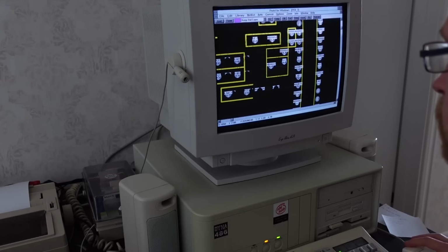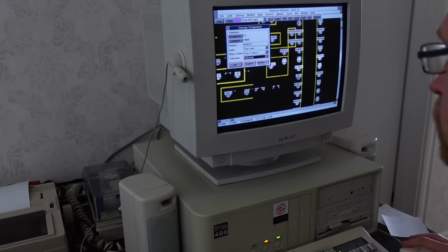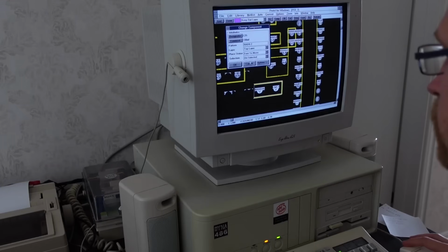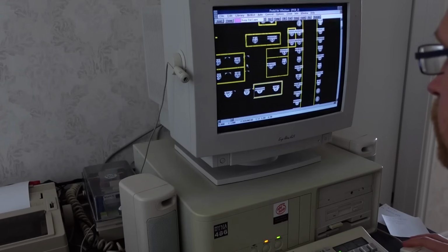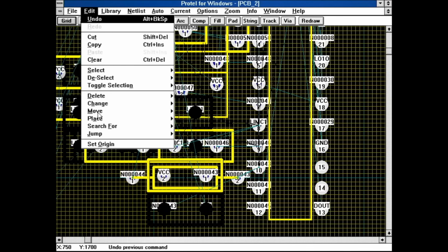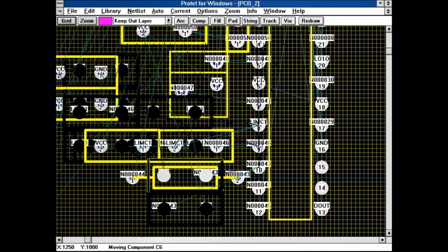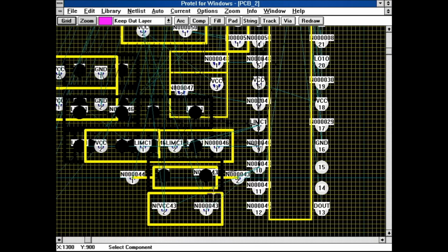Another fun quirk is when you double click on a component. You shouldn't move your cursor until the dialog comes up. It doesn't look at where the cursor was when you double clicked. It looks at where it is when it's done thinking. Another thing you might have noticed is that the graphics look all garbled and corrupted. It doesn't redraw the screen unless you tell it to, and the partial redraws it does aren't exactly perfect. There's a reason why they put the redraw button right on the toolbar.